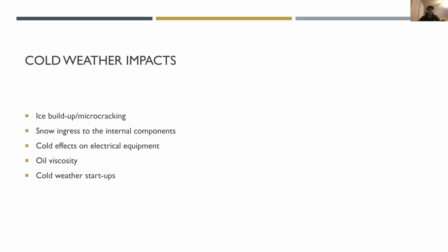Oil viscosity can also play a big factor because in cold weather, if the viscosity is not at the correct levels, the oil is not able to properly lube up the gears and can cause catastrophic gear damage within seconds of operation. And overall, cold weather startups just aren't good for the turbines.